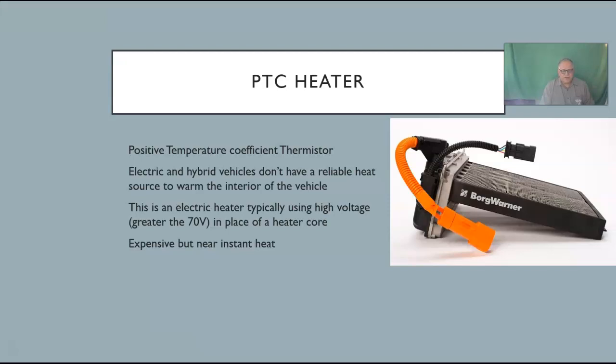So they're going to apply the high voltage to this, and instead of being those elements that heat up and glow like you typically see on a home heater, these are using positive temperature coefficient, or PTC elements. That is, they run current through there, those heat up, and then they're going to have the fan blow by there to bring the heat inside the vehicle. So much more efficient than those home heaters to use these PTC thermistors.